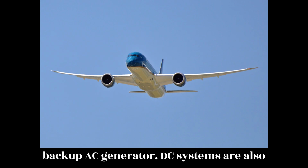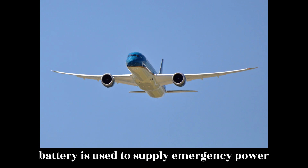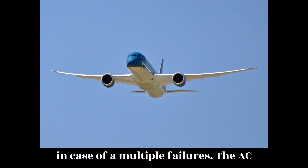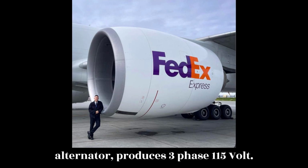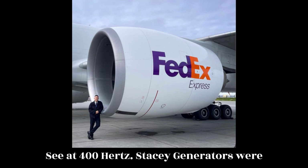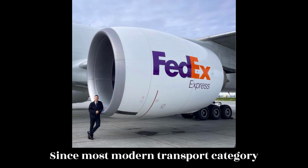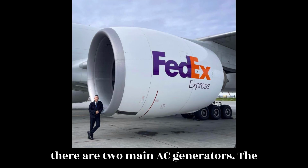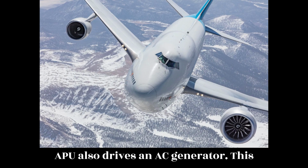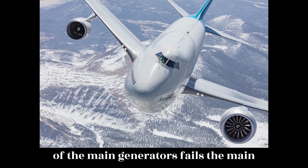DC systems are also employed on large aircraft, and the ship's battery is used to supply emergency power in case of multiple failures. The AC generator, sometimes called an alternator, produces 3-phase 115-volt AC at 400 Hz. AC generators were discussed previously in this chapter. Since most modern transport category aircraft are designed with two engines, there are two main AC generators. The APU also drives an AC generator. This unit is available during flight if one of the main generators fails.